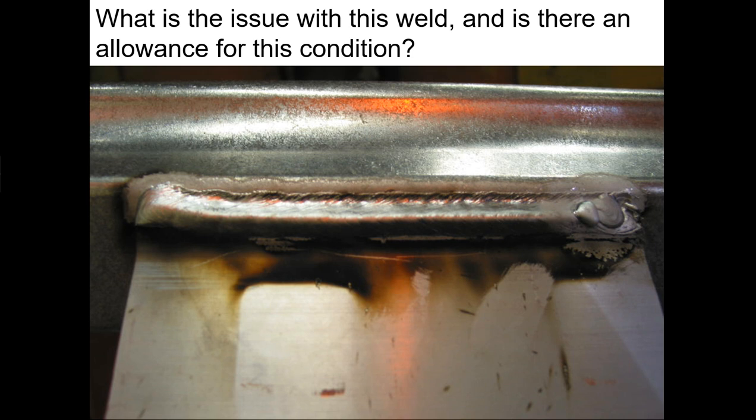Now, this is a condition we refer to as undercut. Undercut is probably, especially when it goes along an entire area like that, the absolute worst thing you could possibly have. Because you may as well put a sign on it that says, crack here. We've created a weak point.